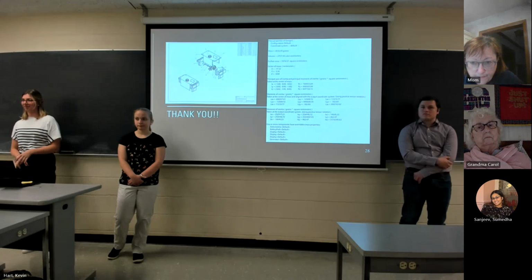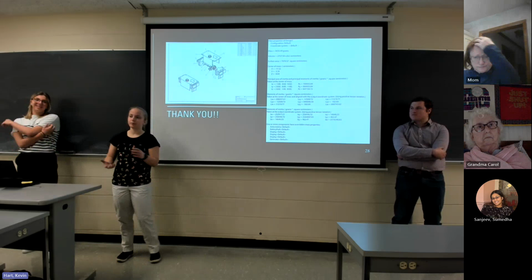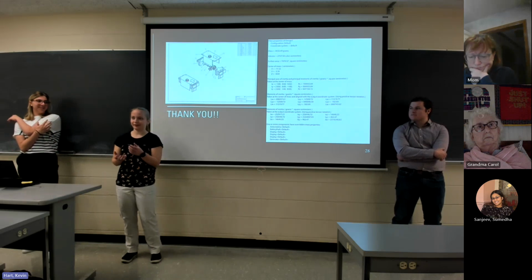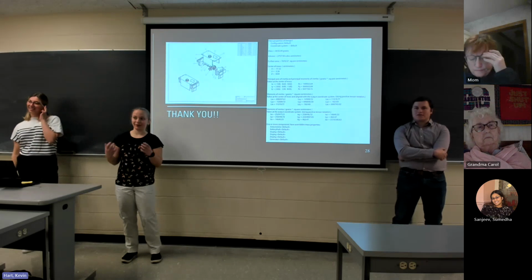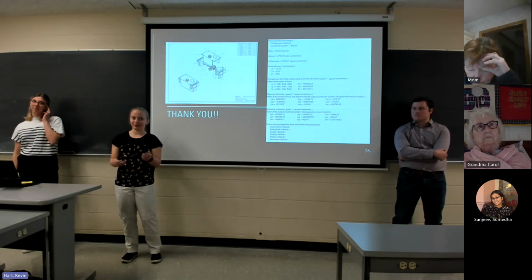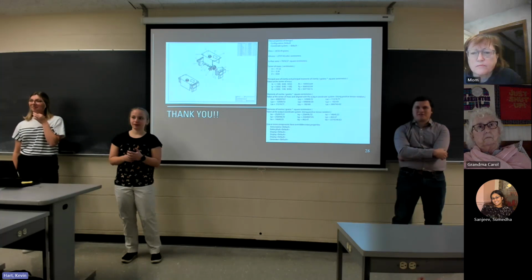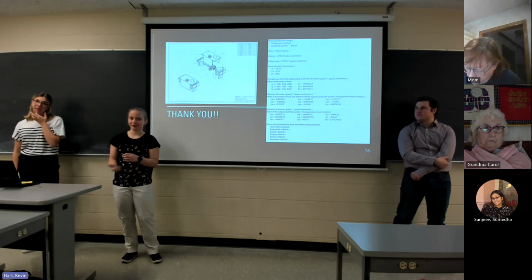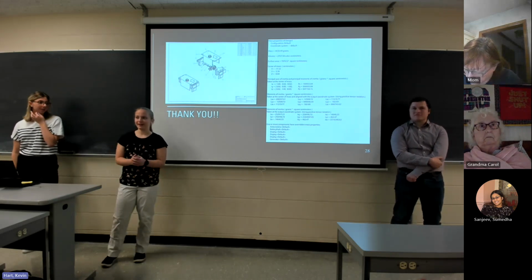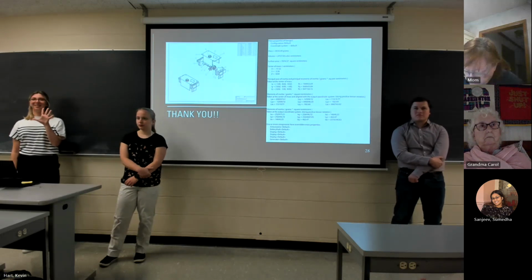The efficiency was really that low? Yeah. The design we purchased was made to be run in a kitchen sink. So it was way undersized for the amount of fluid and water we were getting from the flow bench. The motor was also scaled to just light up a single LED or another small motor. In addition, the buckets were not designed well. It was tiny, way under, about the size of our hand.